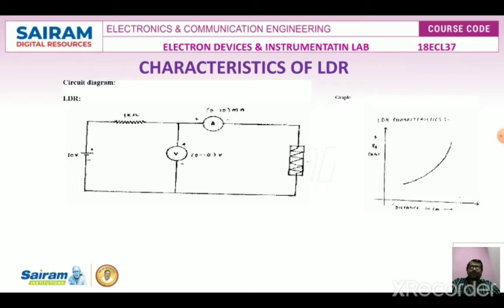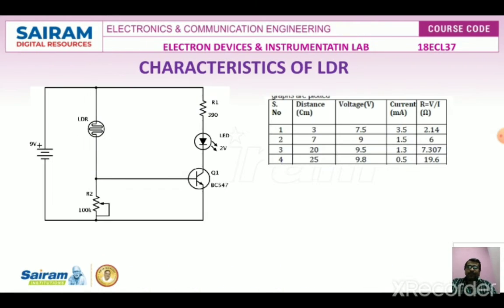We have to choose the RC time constant greater than T, so that the tilt in the waveform is negligible and C does not discharge. Let RC be 10 times T, where T is 1 millisecond. So RC is 10 milliseconds.